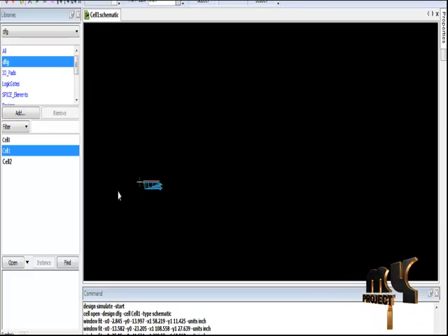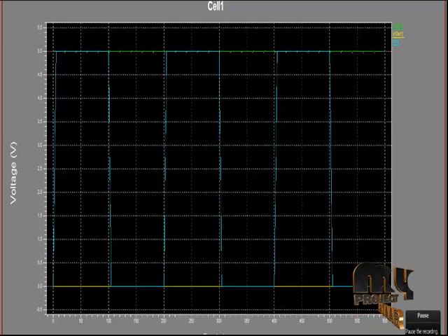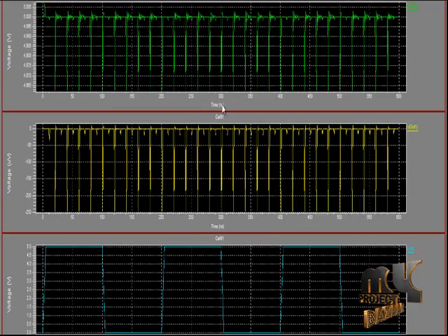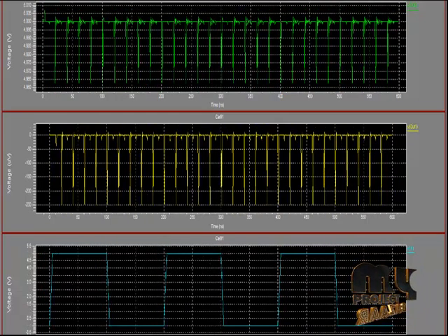Now we start the simulation of cell 1. Click Start simulation. Now display the output waveform of cell 1 and expand this waveform using the expand option. Vin is the initial input. Vout and Vout2 are the outputs of a mux. This output of the mux is directly applied to the path selector. This is the flow under the electrode driving circuit option. This path selection will be run in cell 2.